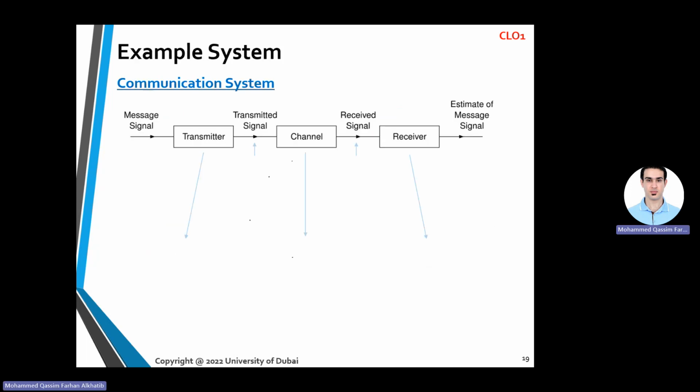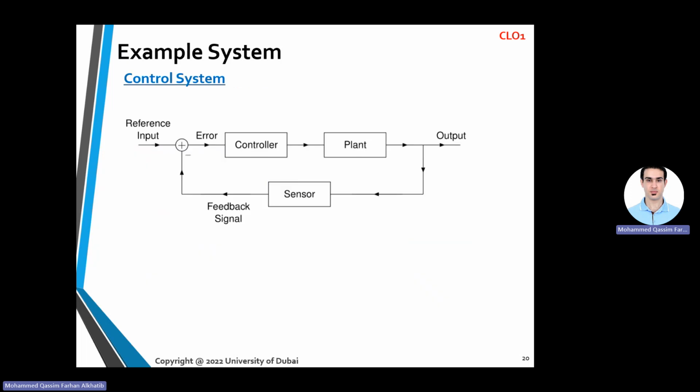We've seen that already, the communication systems, all kinds of signals, and this is in control systems, where like a typical feedback system that you have the reference input, you will feed it to the system, you have a controller, you have a plant, and you will get an output. To get the output as close to the reference input, you take a portion, that's what we call a feedback, a portion of the output, do some certain analysis using a sensor, and feed it back to the system.